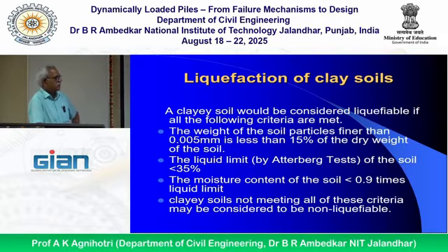Moisture content of the soil is less than 0.9 times the liquid limit. Clay soils not meeting all of these criteria may be considered to be non-liquefiable. So normally that liquefaction problem is faced in loose or medium sands.